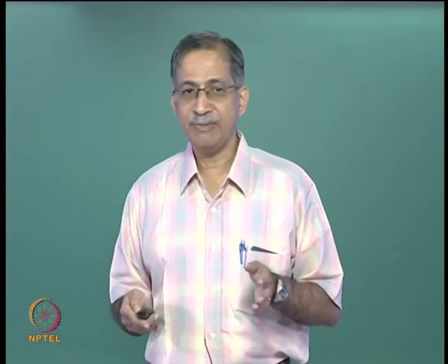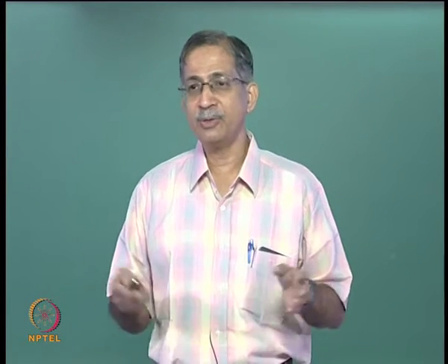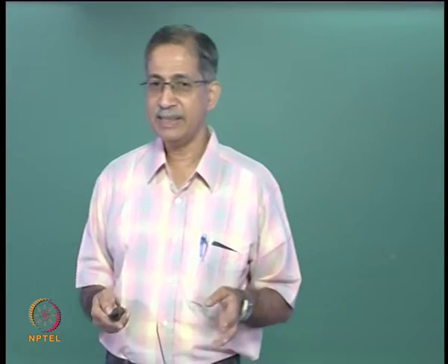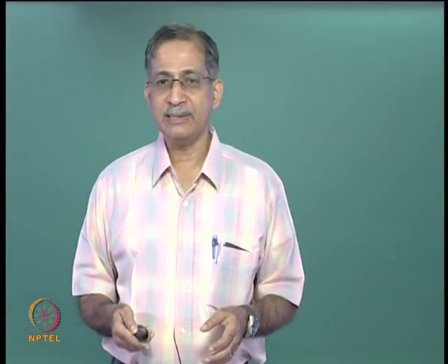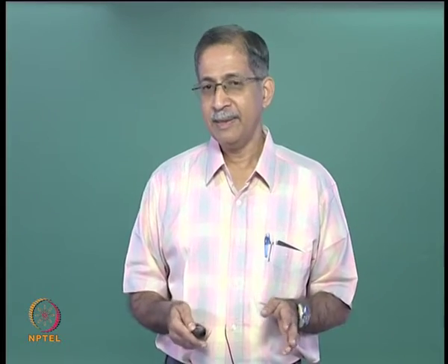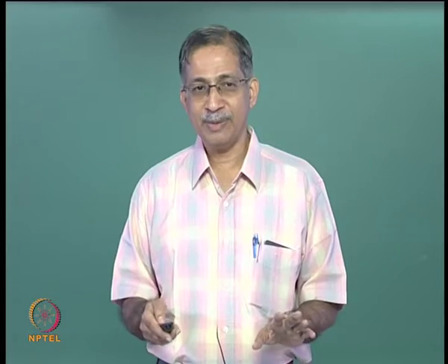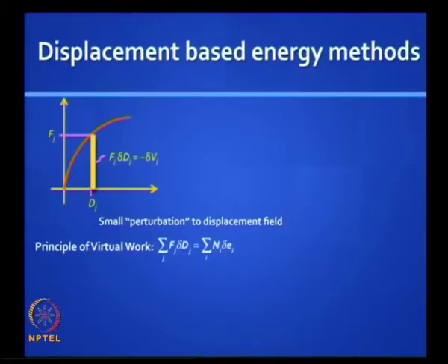You get another set of principles when you disturb the force field without disturbing the equilibrium in that field, and those principles are related to complementary potential energy, and you have a 1:1 relationship with the principle of virtual forces. This is a kind of a big map, an integral map where you see all the energy methods, and we will take a quick overview of these principles. We will first look at the displacement based energy methods.